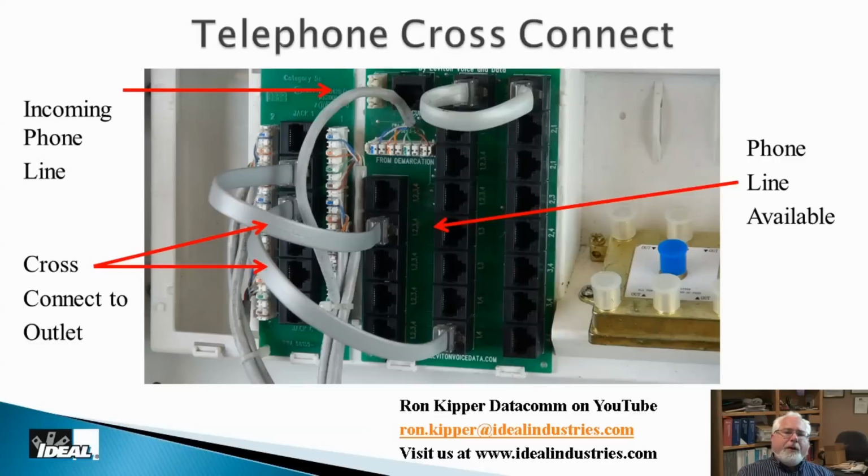And another way of doing this, if you want to maybe look into more structured wiring ideas for the building, is to utilize what's referred to as a cross connect. Now, in those other examples, we're kind of interconnect. We're bringing a dedicated run, and that line is going to be nothing but a phone line because that's what it's terminated to, back at the phone board. Well, you can also utilize what are called cross connects in a lot of these residential panels today too.